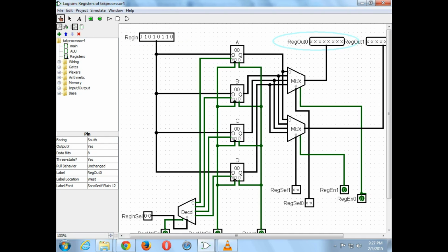okay, I know what you're asking. It has to do with the clock signal. What does it take for a register to update? It needs a 0 to 1 transition on the clock pin, and there's one more thing, which is the enable. Right. So remember that part. So let's say we set up, this is the result of a calculation, and the registers are already open here. So we have the whole circuitry set up.